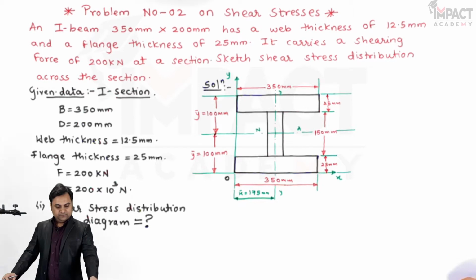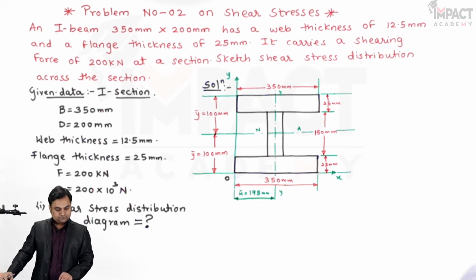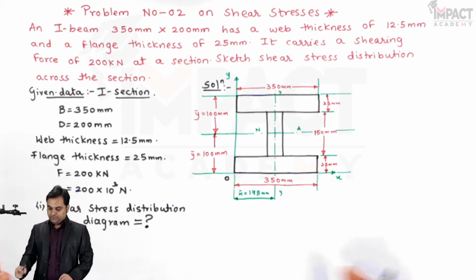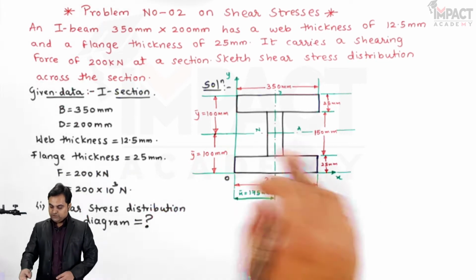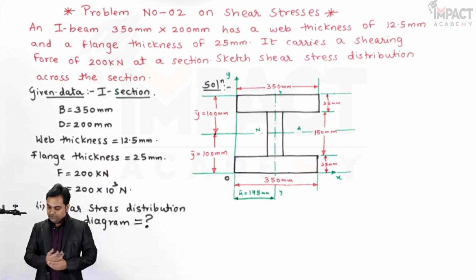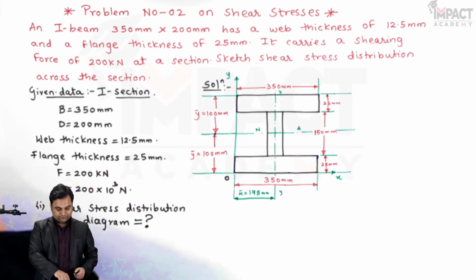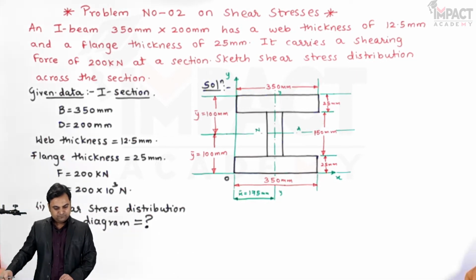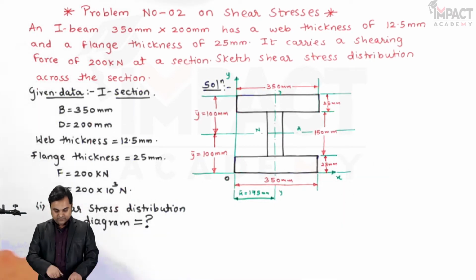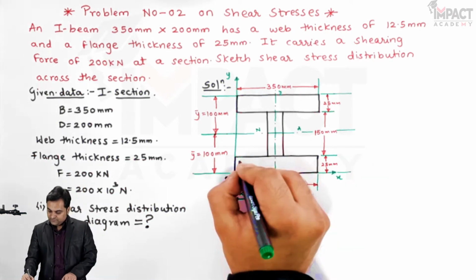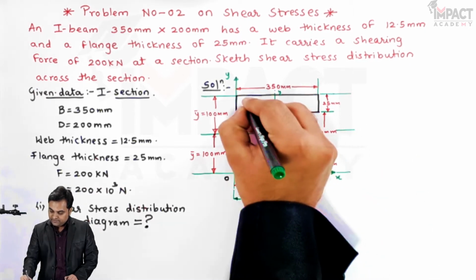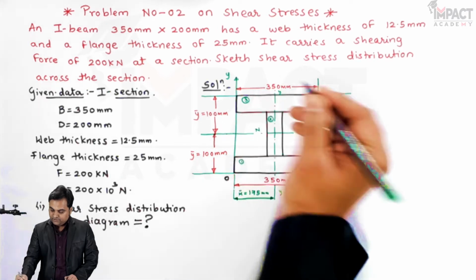Then after reaching up till here, the next thing in this problem would be to find the moment of inertia of this complete section, that is after the location of y bar. The next step would be to find the moment of inertia, and for that I'll divide this figure into three simple areas, that is area of this first rectangle, here we have second rectangle, and even the third rectangle.